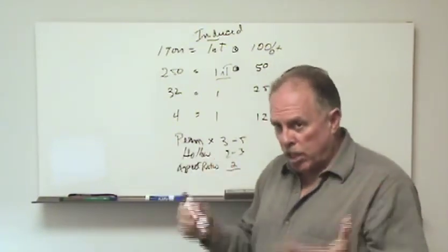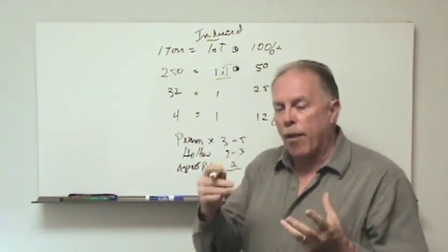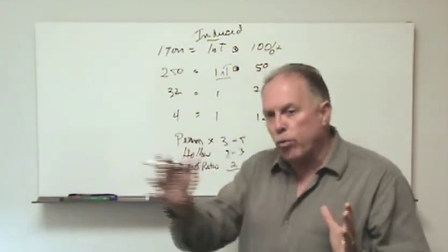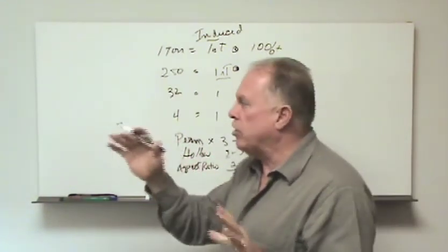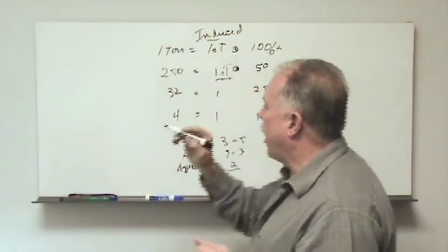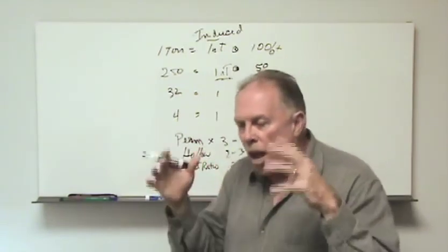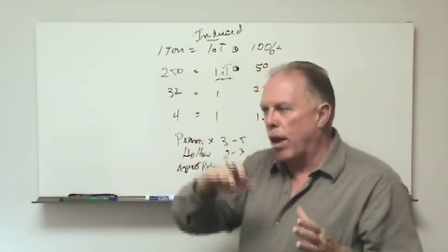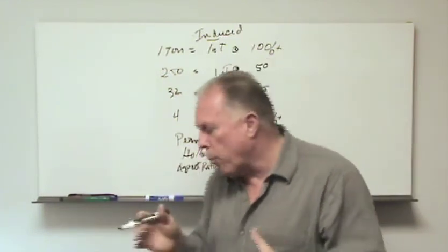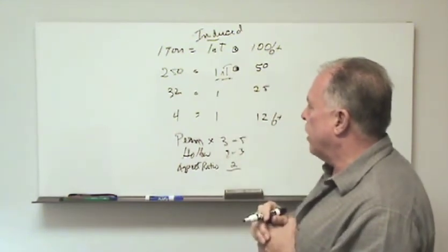These are sea waves. These are conductive water waves which have the ability to generate small eddy currents as they move through the Earth's magnetic field. So all of these generate some noise, and they are external to the magnetometer and being measured by the magnetometer, and they are not coherent, meaning that they do not repeat normally in a way that we could filter them out. So what we would want to do is probably set a lower limit of 1 nanotesla.